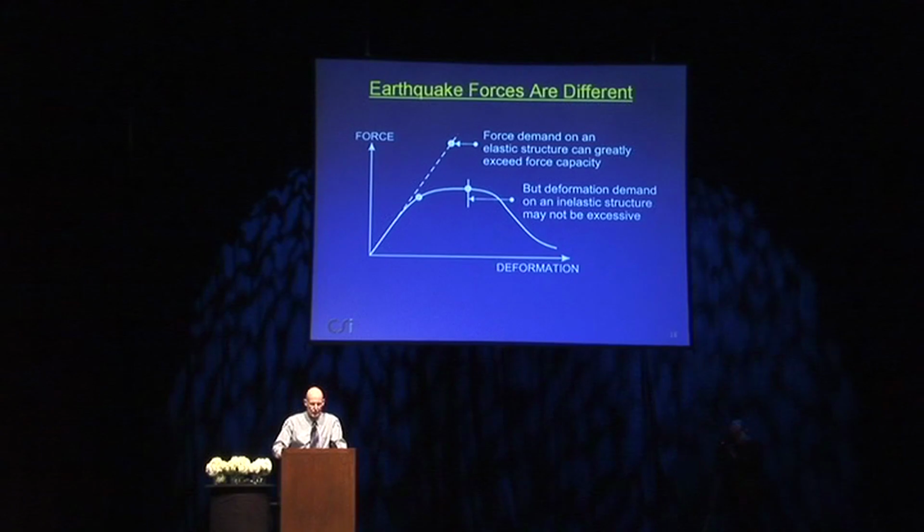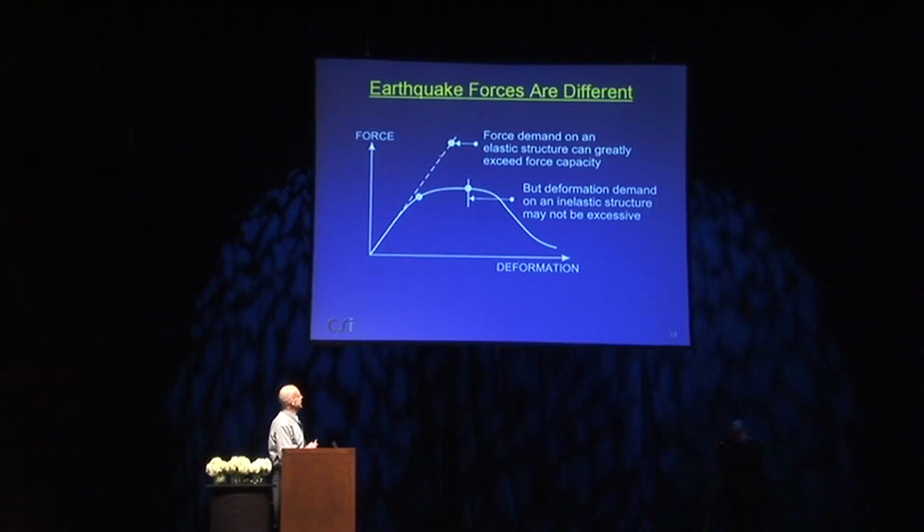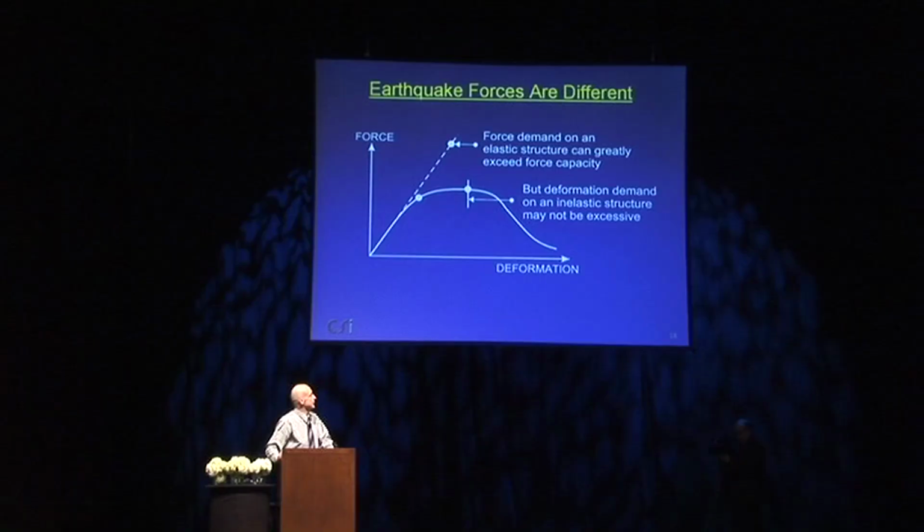Now, earthquake forces are different. The conventional wisdom says it's not economical to design a structure to remain elastic during an earthquake. It will yield under a strong earthquake. So if you were to think of an elastic structure and you were to calculate the force demand on that elastic structure, that could substantially exceed the force capacity or the strength capacity of the structure or some or even possibly all of the components.